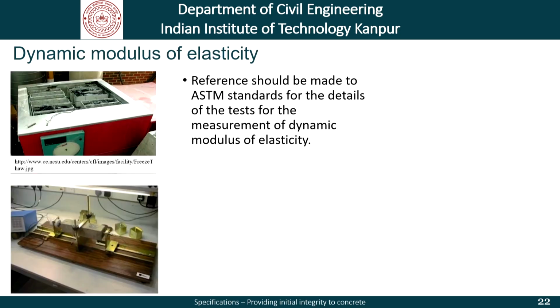Now, as far as the measurement of durability factor is concerned, and the performance of concrete as far as air entrainment and freezing and thawing is concerned, one of the important parameters that we need to measure is the dynamic modulus of elasticity. I request you to go through ASTM and other standards which tell you how these tests are to be carried out. What is shown here is a chamber where concrete specimens are exposed to cyclic freezing and thawing under standard